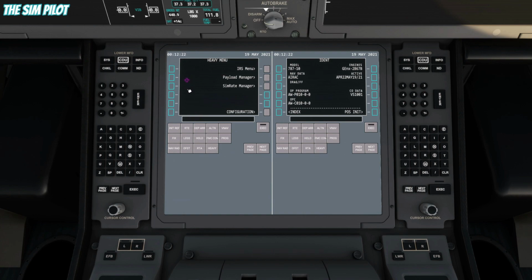We will look into the flight plan and I will talk about some more functionality brought by the Heavy Division team into the FMS. Like holds, this aircraft can fly holds now. Or you have a VNAV page where we can set the cruising altitude and the speed for climb and cruise. I think we cannot do anything for the descent yet, but yeah. So this VNAV page also works, the holds page also works. You can set up a hold, but we don't have any flight plan, so it's not going to show anything to us yet.